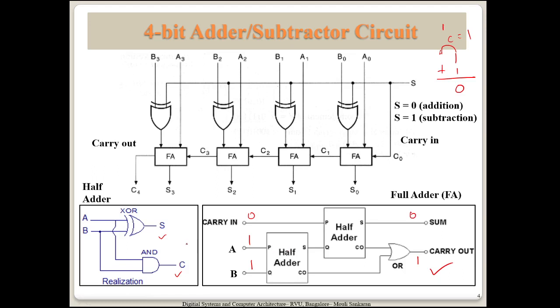Now let us backtrack and see whether it is really happening. Inside of this, the half adder is there, so you can assume that this is an XOR. What will happen? Because if you give 1 1, XOR will be 0. Now let us fall through this. This is going to be XOR again. Now this is again 0 0, so the output will be 0. XOR output will be 0 for the same input. So the sum is correct.